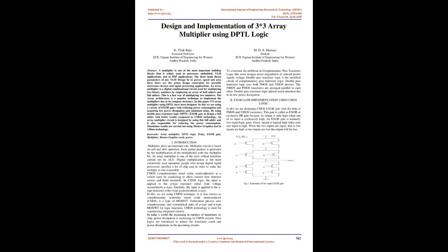to CMOS technology. An array multiplier circuit is designed by using this full adder, and it is also responsible for reducing the power consumption. Simulation results are carried out using Mentor Graphics tool in 130 nanometers technology. Keywords: array multiplier, DPTL logic, delay, EXOR gate, multiplier, Mentor Graphics tools, power.